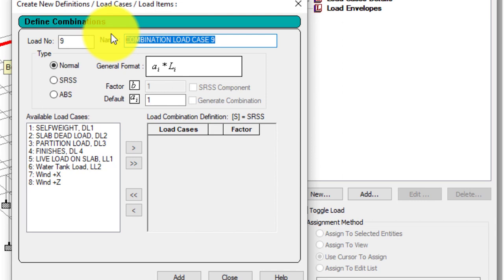Okay, now the other one is ultimate geotechnical. That one is for the geotechnical design, the foundation design itself. Geotechnical load combination is where we get the parameters for our geotechnical foundation design. Then the fourth one is structural load combination. That one is for member design, so structurally, how the structure reacts. That's where we use the maximum load factors, for us to have member design able to withstand the forces when they are increased with those factors. So let's dive into it.